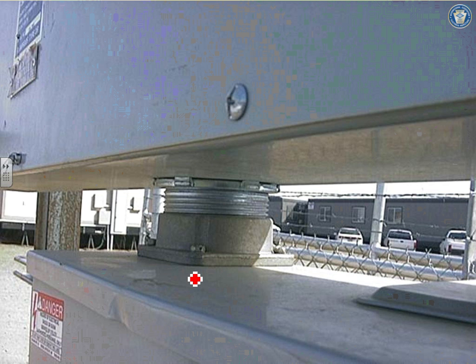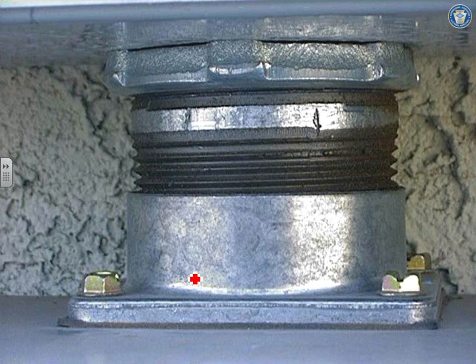Here's an alternative. Where's your main bond, where's your supply side bonding jumper? The hub itself is your supply side bonding jumper. Does that make sense, the supply side bonding jumper? Really, the supply side bonding jumper makes a big difference, guys, when you're paralleling conductors, really a big difference. Coming to the bottom of a switchgear, a big difference.